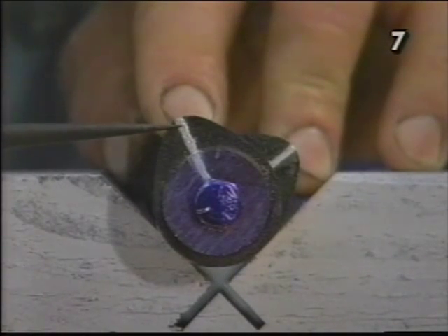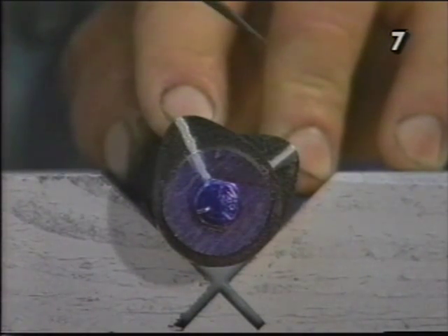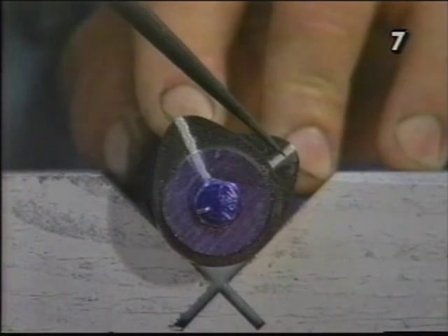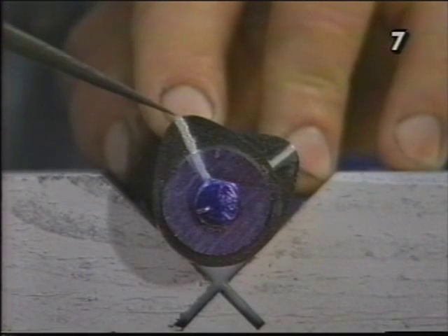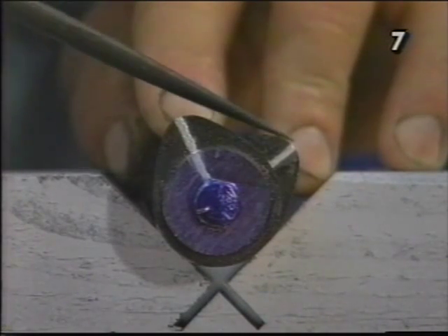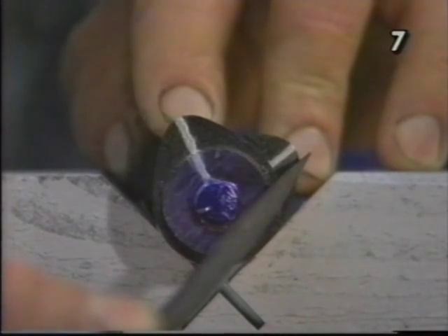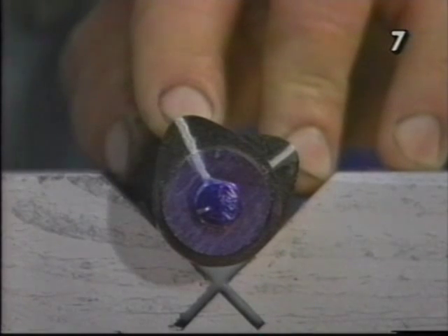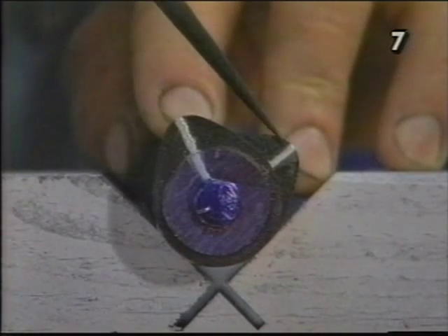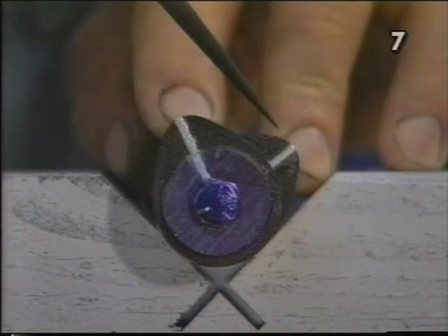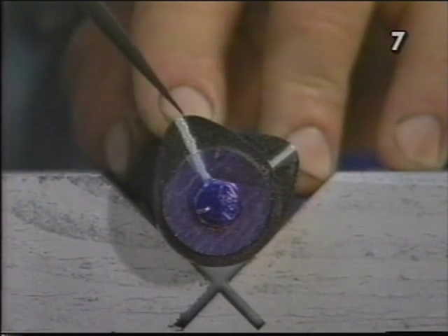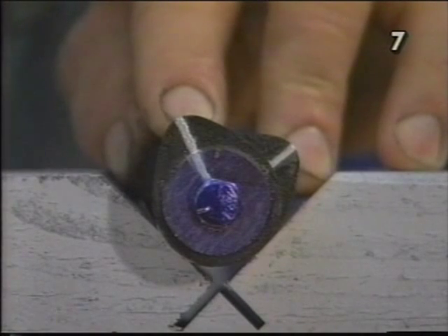The distance between the center line of the intake lobe and the center line of the exhaust lobe of the same cylinder is what is commonly referred to as lobe center, or as we have discussed, we're going to call it separation angle, because there is a separation of distance between the center lines of the two lobes. By using separation instead of lobe center, we can easily differentiate it from lobe center line. The closer together the two lobe center lines are, the more overlap will be built into the camshaft.